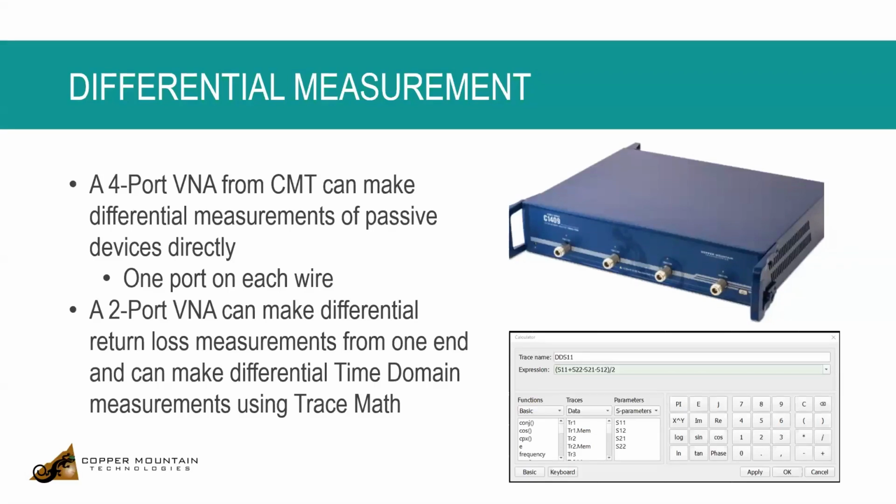How is that useful? Well, you can measure from one side and use a time domain, and you can look at a differential line that's moving along a board, goes through a connector, comes out the other side. And so this 18 gigahertz 2-port VNA is sufficiently prepared to make time domain measurements on a microstrip, a strip line, coplanar waveguide, or a differential line.